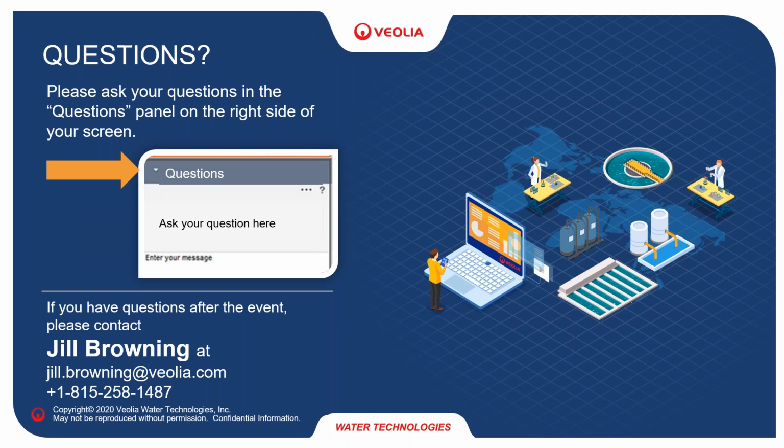Okay, another one is, can influent water be used instead of effluent to inject gas bubbles? Preferably, it's better to use effluent water, since it doesn't have any of the contaminants in it. But also it depends on the application, depends on if there's already a pump present for the feed, or if there's pressurized influent coming in. Preferably, because we have to put in an effluent pump, it's more efficient to use the effluent as the recycle stream for the eductors.